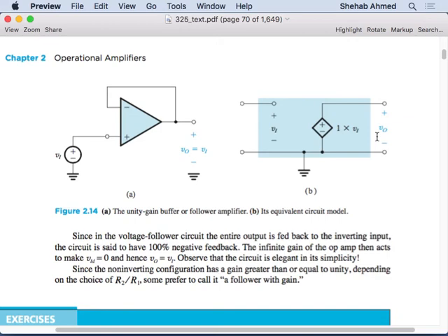And any device is a physical system. You've manufactured this thing on a chip, right? You cannot have infinite current flowing through anything, right? Only superconductors can allow infinite current to flow, right? So this is not a superconductor, it's silicon. So silicon means it has voltage drop. It has voltage drop means it's a power loss. It has power loss, it means that it's heat. There's heat, then at some point it will burn, right? So everything has a current limit, right? So this is something we'll talk about later, but it's not coming from the equivalent circuit. It's coming from the manufacturing process itself.